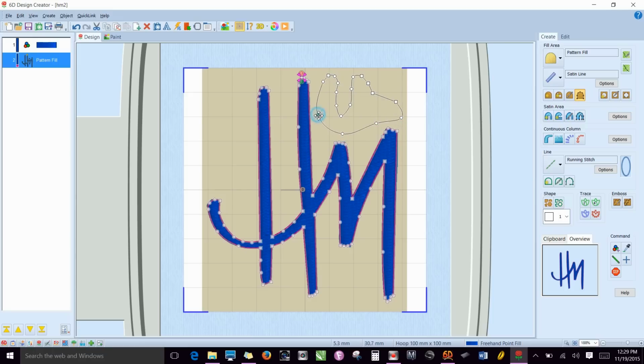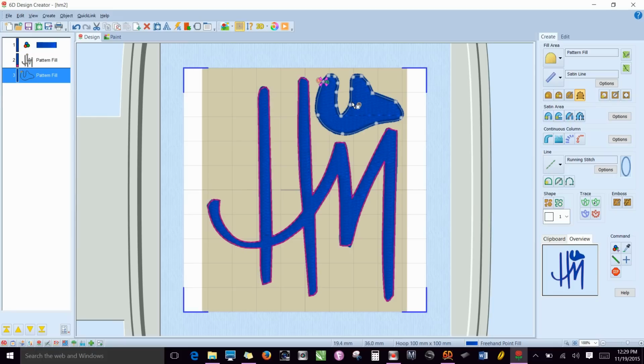So again, you can shape it. And this is what I use the most. When you're done creating the shape, if this is the shape you want, then you right click on your mouse and it will turn it into stitches. Okay, so you're going to left click, and for the square nodes, you're going to control and left click for anything that you need square, and then you're going to right click when you're done and you'll have a shape.